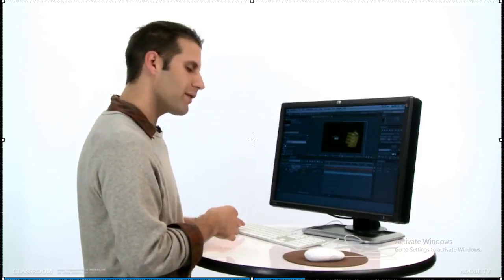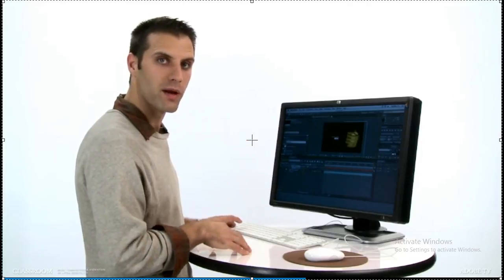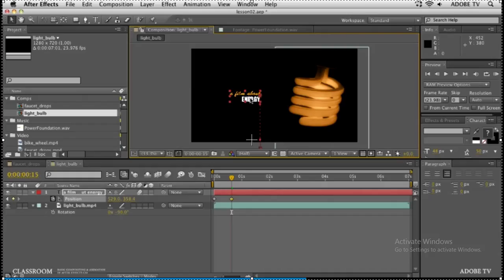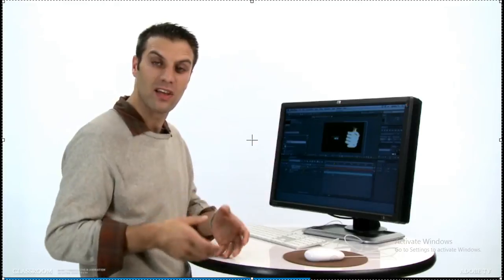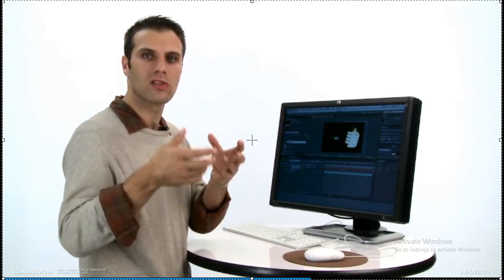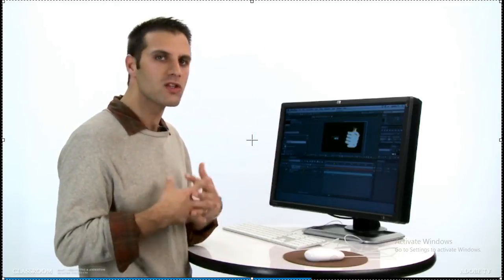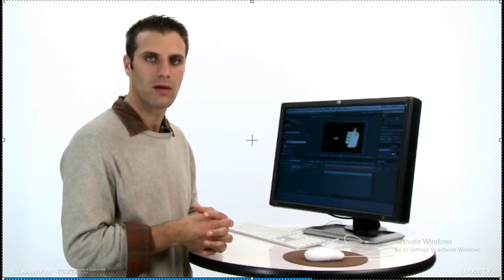So we can use Shift and Page Down to advance another 20 frames forward. I'll click it twice. Shift, Page Down, that's 10 frames forward. Then Shift, Page Down again, that's 20. That means that it rises up in about 15 and falls in about 20. A little bit faster because the elasticity of things moves quickly in the beginning and loses a little bit of velocity over time. This just deals with basic animation theory.